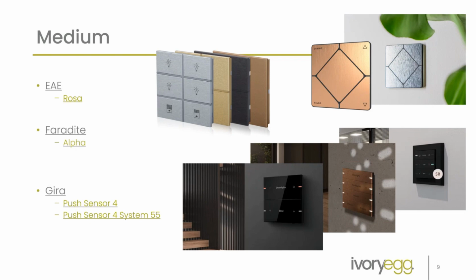Then you can inscribe them with Gira. They have an inscription service, and then you can put text in the middle, and then put like blinds, and then on off, or however you decide to do it. I do a lot of these in the mid range, the Gira push button sensor 4 system 55. You can make them flat or protrude out, and they're good in matte white. They're just a good happy medium for people when they do want that granular control and to still see inscriptions and writing.